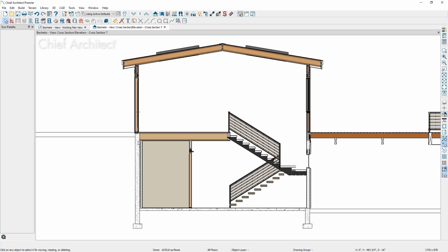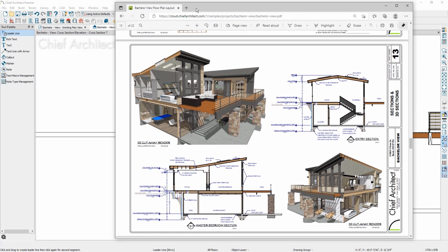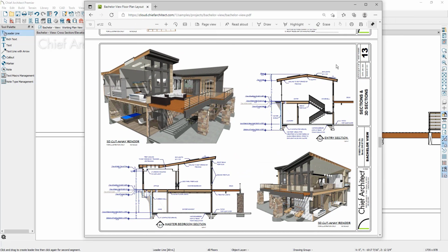And you can see that Chief has added concrete CAD fills wherever that's needed. It's added fills about our wall types, insulation, and so forth. Additionally, you can continue using the dimensioning and text tools and CAD tools to detail out this cross-section however you want to, so that eventually it looks something like this that's available for your completed layout sheets.